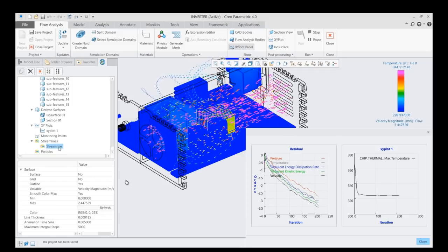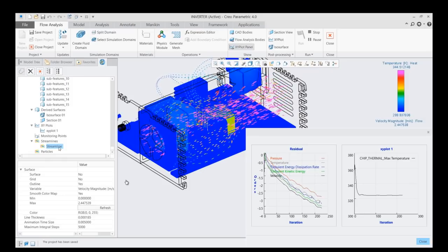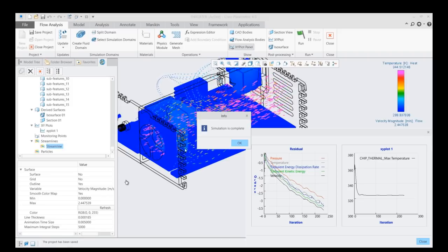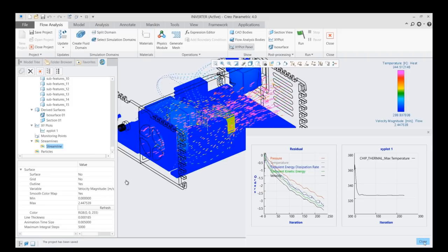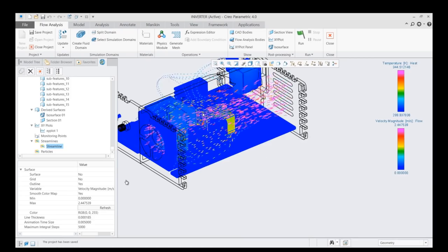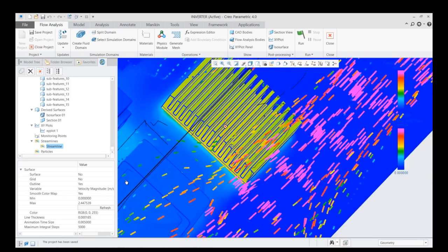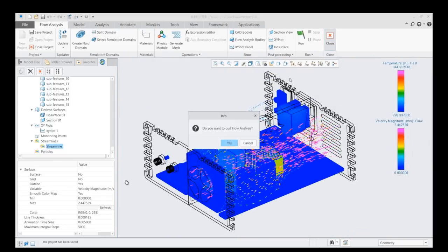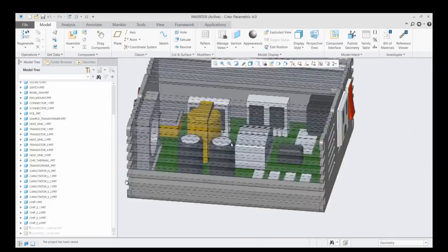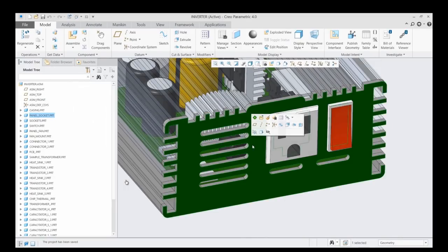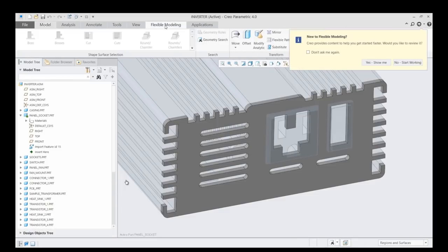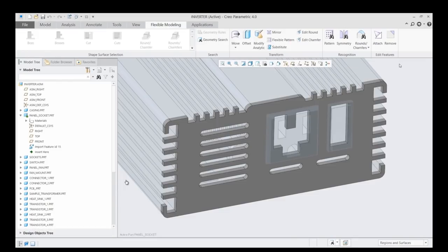One of the things that's interesting to note here is that a lot of the flow that's going into the upper part of the electrical enclosure is very slow moving, and there's not an awful lot of flow actually in that area. Right, now me as a good old engineer, I'm thinking I would like to get more air into this enclosure. And that's the typical thing that an engineer tends to think. An analyst thinks very differently, I think, from an engineer. Engineers think bigger is better, so let's give it more air going in here. Whereas analysts, I think, tend to think a little more strategically.